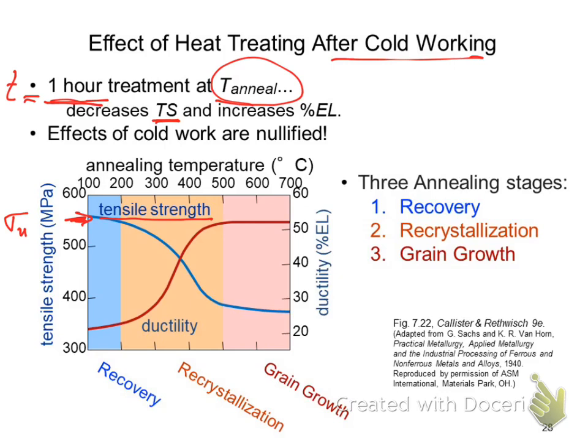Oh, by the way, on the x-axis, we're calling these recovery, recrystallization, and grain growth. This is kind of a way we can also use time for this axis, it can be a proxy for time for these particular regions. So as we hold it for an hour, what happens to this tensile stress? Well, it starts out really high, and then with time, our tensile stress goes down, and we end up with a much lower ultimate strength after doing this procedure, this annealing for an hour.